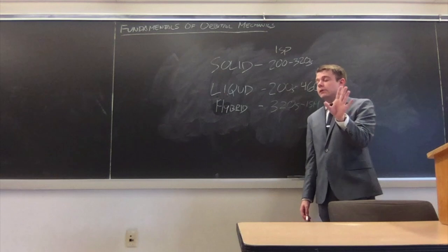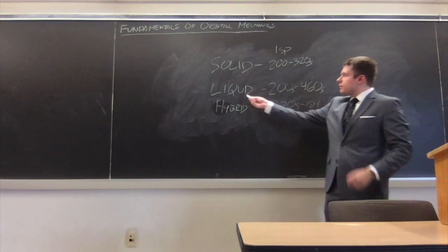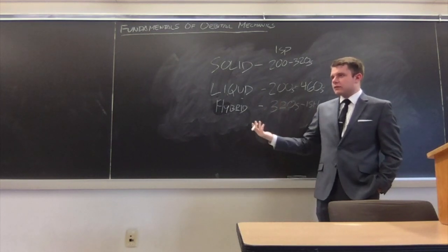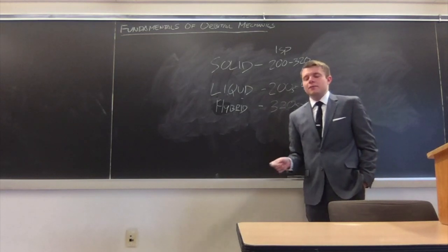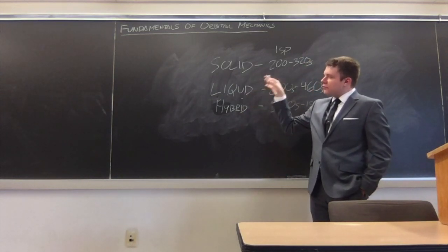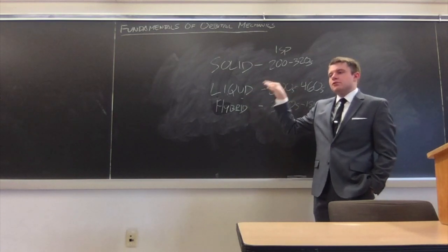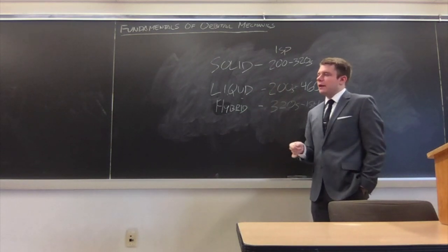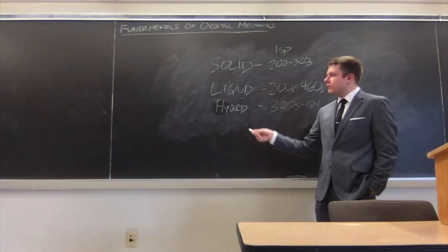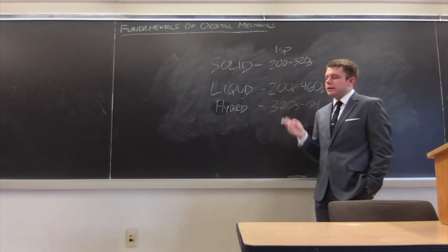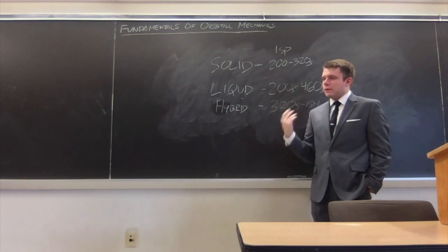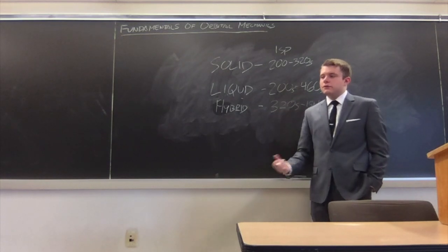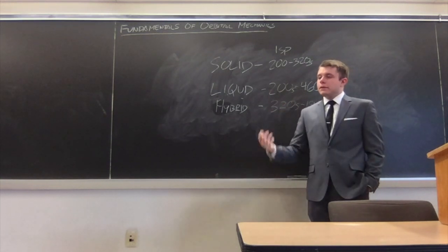And I should probably take a quick detour to talk about cryogenic propellants. So, for the most part, liquid propellants need to be liquid because they're gases that are liquefied. That sounds really bad, and that's a really bad way of putting it, but those are very cold. You don't really have room temperature liquid fuels, with some niche exceptions. And I can talk a little bit about the propellant combinations, and I will do so in a future lecture, but generally speaking, the first ones that come to mind are things like alcohol and hydrogen peroxide, or unsymmetrical dimethylhydrazine and Aerozine 50, or they're a little more exotic.